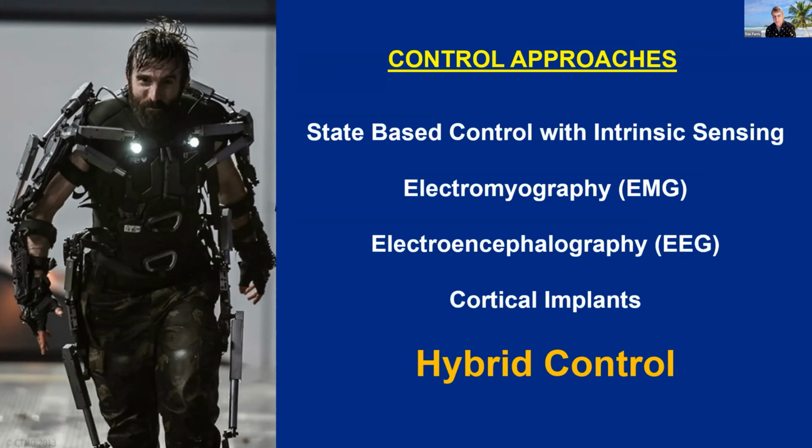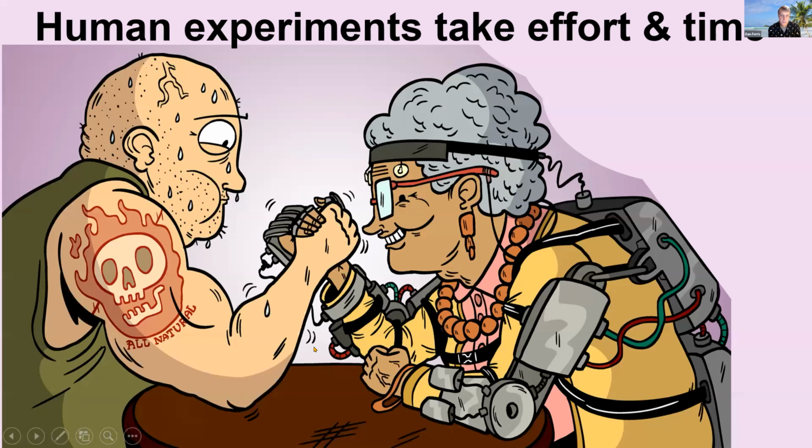One of the biggest things to fight right now is lag. With a lot of exoskeletons, when you put them on and try to move around, you almost feel like you're walking through water or molasses, in that you make the motion and the exoskeleton has to catch up. And that is a difficult thing to overcome. I think in the future, if we try to use all the information we have available, we're going to have more success for the controllers.